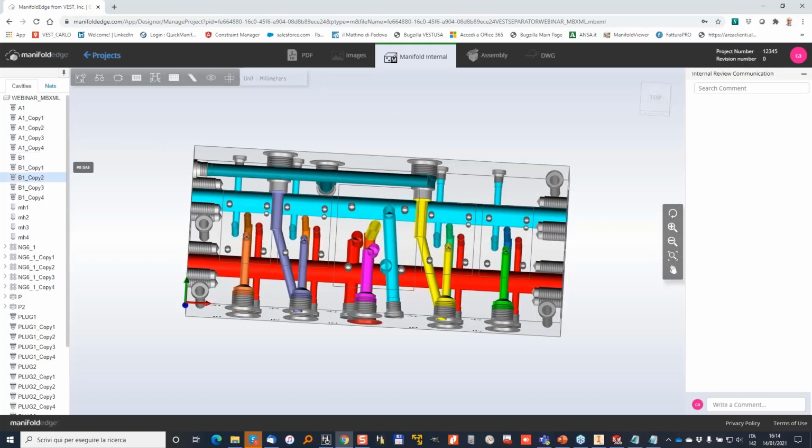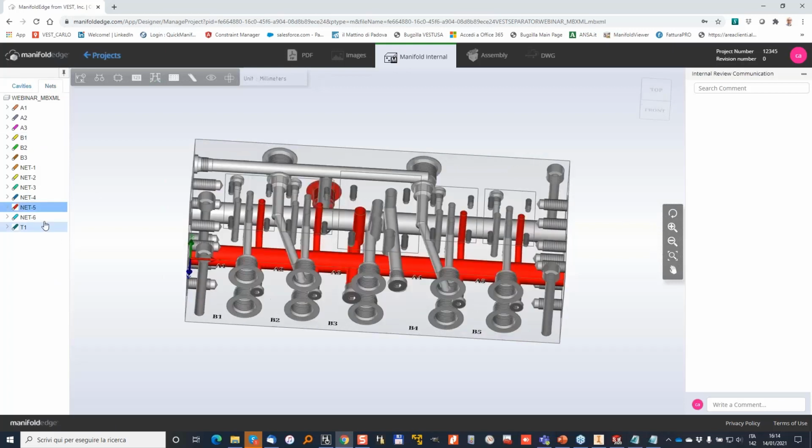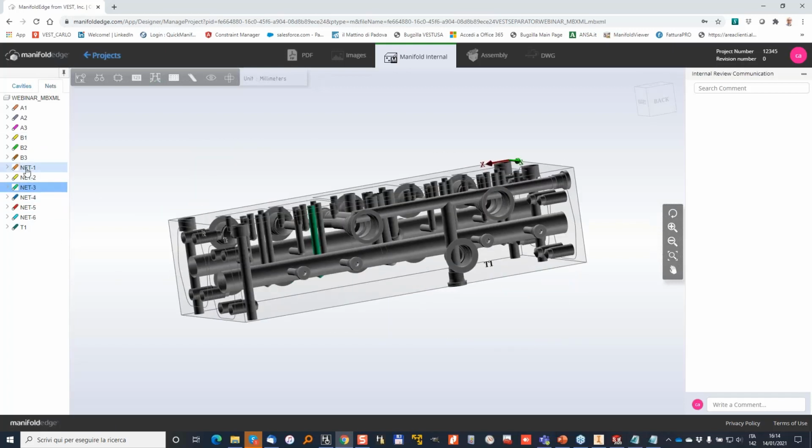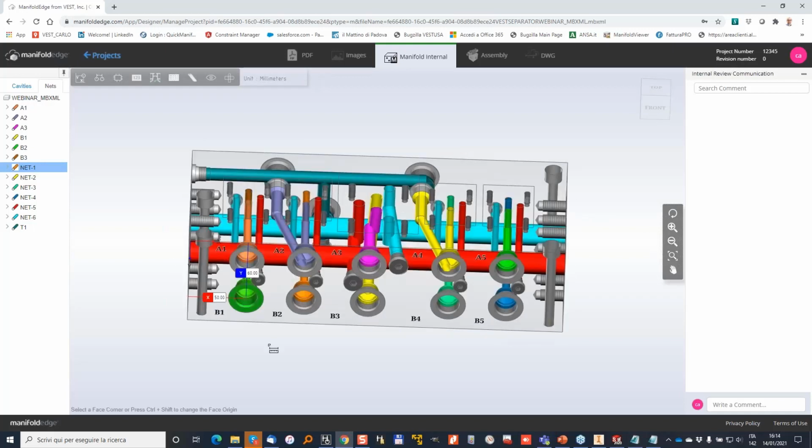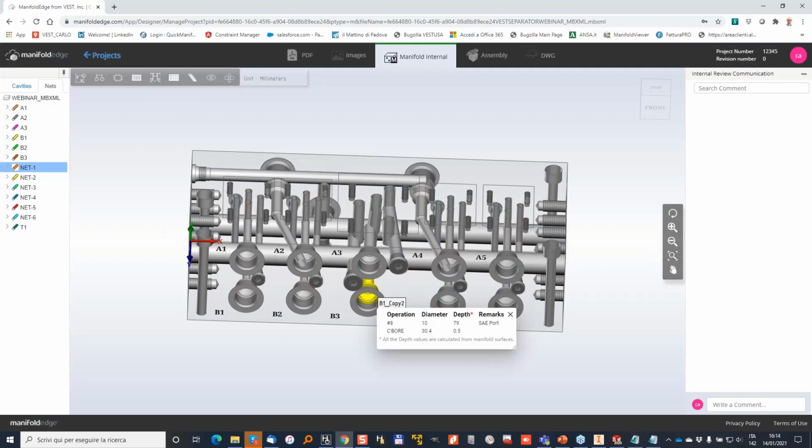and for instance, I can select a cavity, I can view single nets, and I can view the position of one particular cavity. I could also ask what is the machining sequence. If you remember, I told you that the XML information also has the information that you expect in the machining drawing from MDTools. So in this case, we can see that this is a -8 cavity with a spot face, and that's a SAE port.